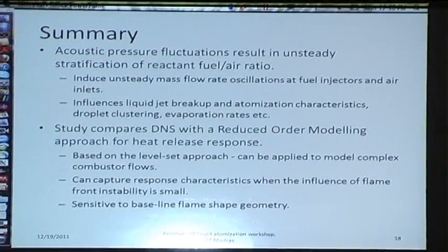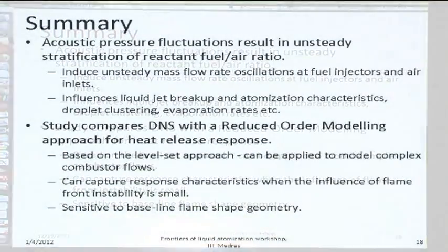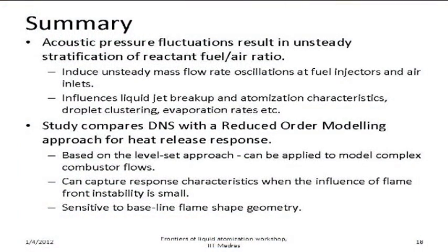So to summarize, we can get unsteady fuel air ratio stratification in gas turbine combustors because you have interactions of acoustic waves with sprays and maybe air inlets, which influences the local mixing. And a comparison between my reduced order modeling and the DNS suggested that neglecting gas expansion works in some cases, which is good news. But the bad news is it won't work everywhere.